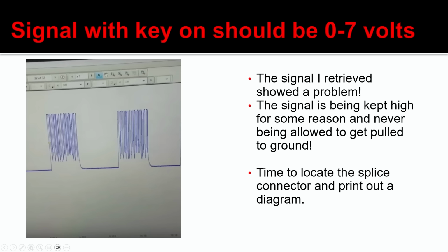I could have stretched it out and seen the information packets a little wider if I had checked the time base. I was just looking for a good go or no-go type of signal. And this was definitely a no-go signal because it never went low, right? That whole communication line was staying higher than the 0 volt threshold. So I knew I had a problem.